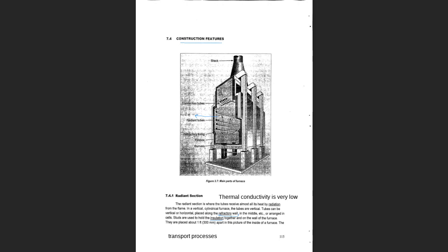لكن مثل ما ذكرت يا إخوان, inside the firebox, because you don't want to lose heat to the surrounding or to the atmosphere, to minimize heat you have to have refractory walls that can be utilized in minimizing heat losses because they have very low thermal conductivity.